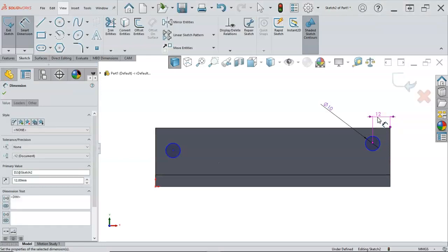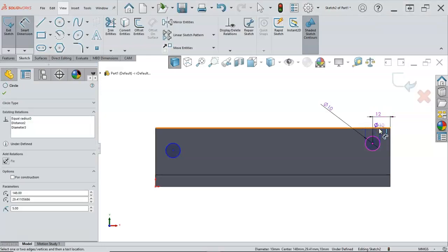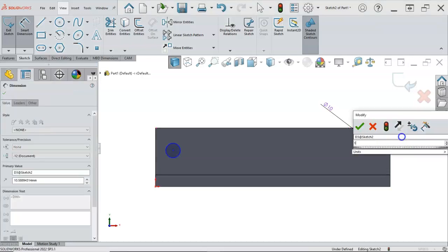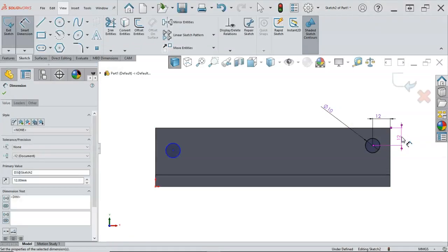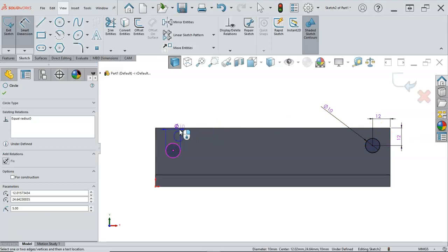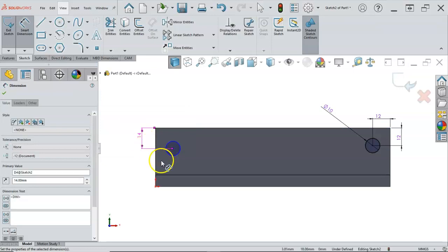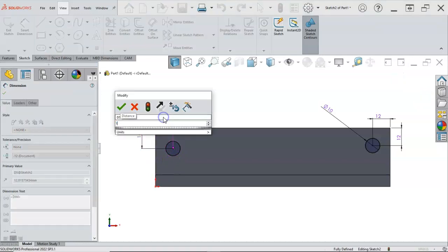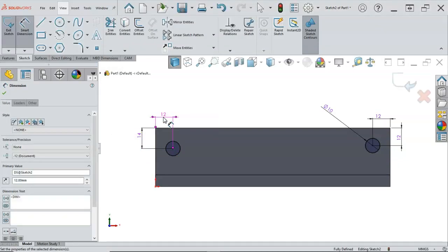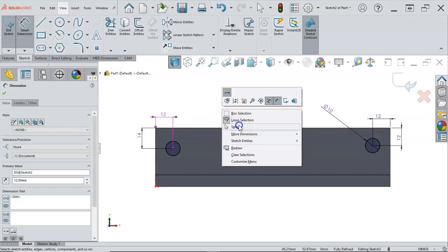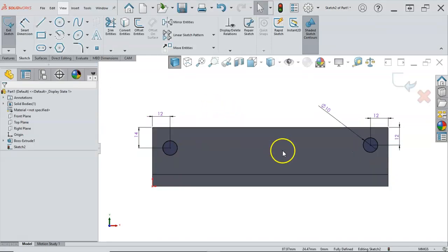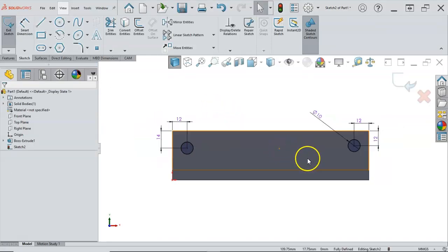As a general rule, if I do not include the fillets and chamfers in the sketch, they pretty much go in last. So 14 millimeters, and we're going to stay with the 12 off of the end, just so that there's a little room, and looking at that, might be 16, I don't know. Might not be 40 either, but we'll have to figure that out as well.